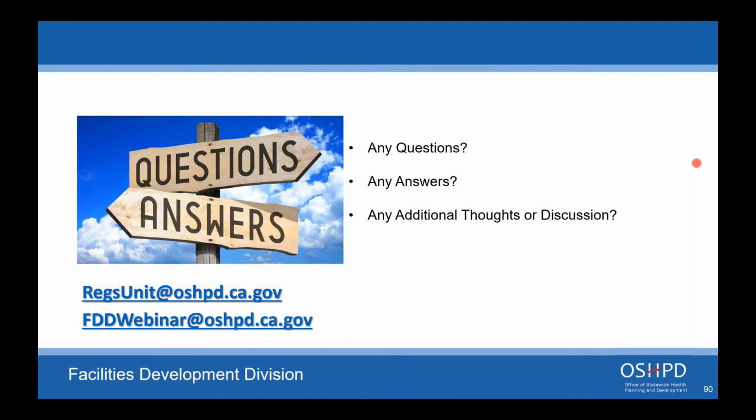Very good. Last question as it pertains to OSHPD 1R. Does this apply to behavioral health systems with patient and acute care, but not medical? If I understand the question, you can put behavioral health patients in a 1R building. Even though it's an acute care psychiatric, it can go in a 1R building because you don't have the requirements for the NPC SPC ratings. Same with the skilled nursing facility.